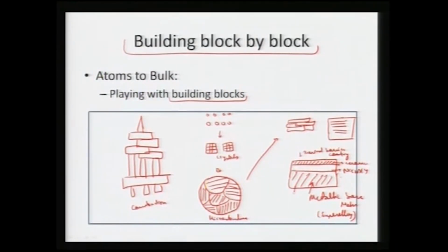So, what we can see, this is a load bearing component. So, it is bearing the load. This one serves as an interface, and this takes most of the thermal load. Now, this base material is protected from the environment, from oxidation or even from thermal load, by this ceramic layer, because ceramics can take very high temperatures, and it has an interface to bind the ceramic layer with the metal, and then this metal, or it can be a super alloy, can take the entire load for running the turbine at very high temperatures.